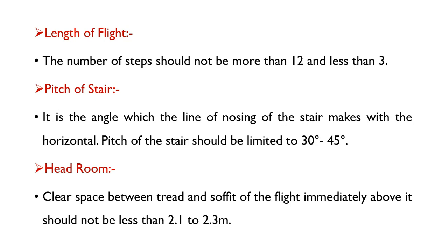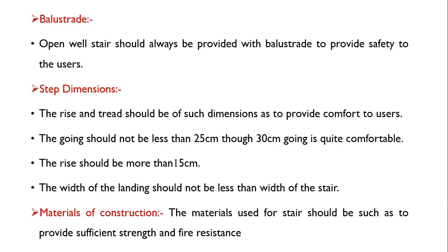In that case, if he or she is moving with raised hands, they should be in a position to use the staircase comfortably. So it is called headroom. Minimum is 2.1, and generally 2.2 meter is provided. So this is regarding headroom.